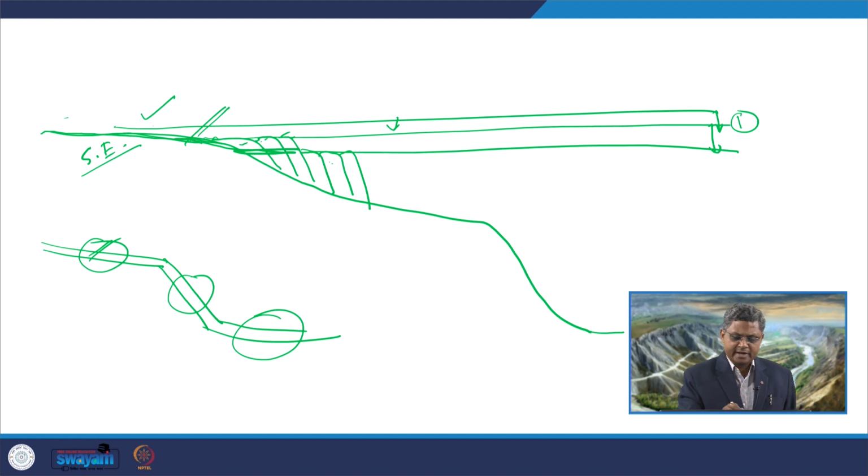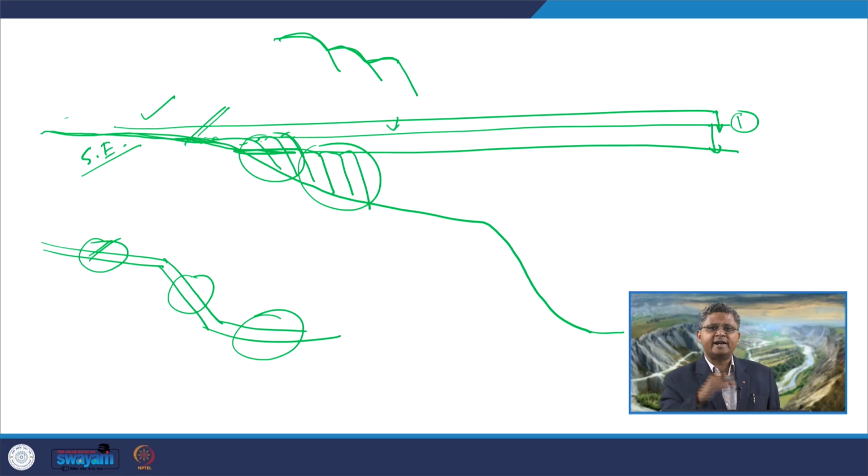So, what we are getting over here is straightaway the delta front deposits, successive delta front deposits which are offlapping in nature, and that offlapping surface is nothing but the erosional surface. So, delta fronts are actually truncated at their top without any delta plain. So, we are getting a delta, but the top part of that delta is truncated by subaerial erosion, by the subaerial unconformity, and we are only getting the delta front, and this will continue up to the shelf edge when the river system will reach up to this, and we get the subaerial unconformity continuing up to this point.